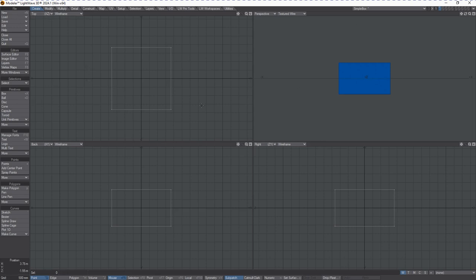So for example, this box, let's say we want to do something a little bit more exciting with it. Let's hit Control K, pardon me, and we'll do a couple of slices here. This is the knife tool, and when you drag it across geometry, you will see that you get additional segments placed into it. Now, this is all fine and dandy, but why would I want this? Well, I'm going to put a couple more in here,